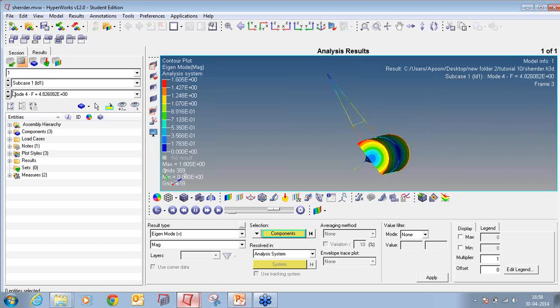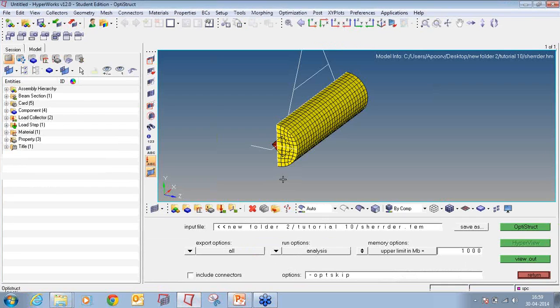So as you can see, the third and fourth modes have frequencies of 3.9 and 4.8 Hertz, somewhere around. So we will use those shape changes. This is more useful for us, and we use them to see how the performance goes. So let's start with defining the design variable and beam cross section property. First we will define the design variable using the size panel.